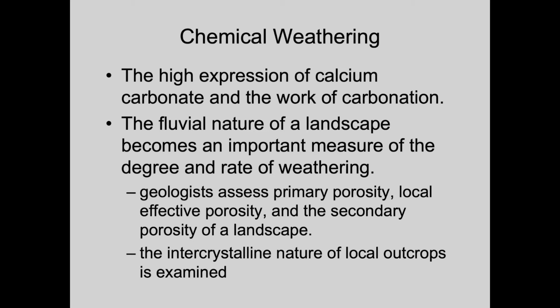The initial understanding that we have of flow as it relates to limestone landscapes and their chemical weathering is generally measured in terms of primary porosity of the bedrock itself. So geologists will generally start their study of a karst environment by looking at the physical makeup, the mineralogy of local bedrock, and they'll specifically conduct experiments that will closely examine the porosity of that particular local bedrock type.